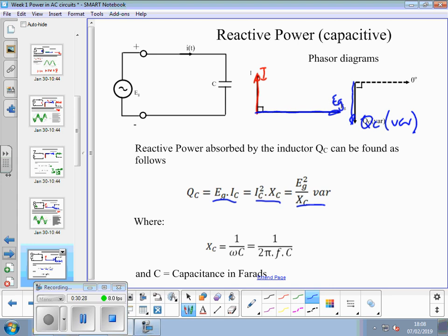What you must get from this is, if you're going to use one of those formulas, it must be that voltage is isolated and all of that voltage is across just that component. Which usually isn't going to happen, because you're usually going to have some capacitance and some resistance as well, maybe some inductance on top. Alright? But if you can isolate it, you can use those formulae. And that's where XC is equal to 1 divided by omega C, or 1 divided by 2 pi FC.